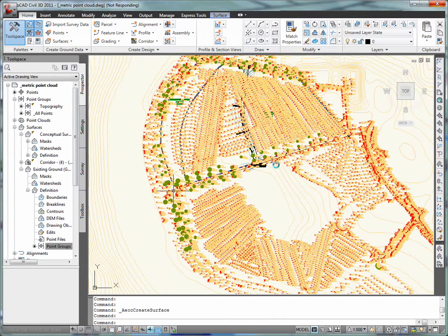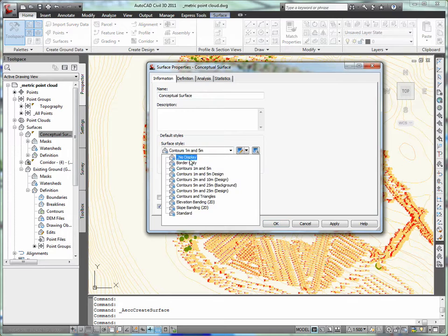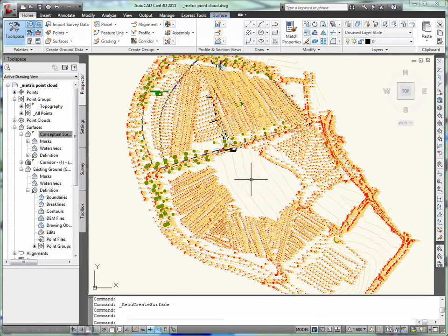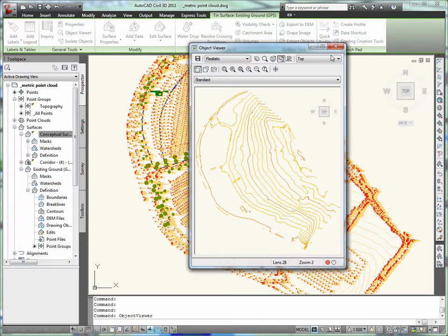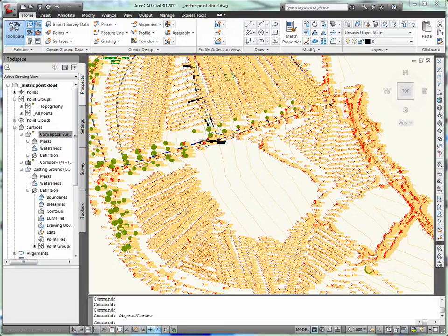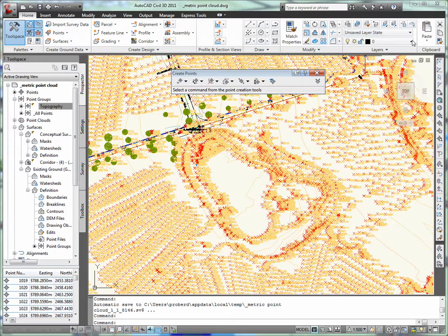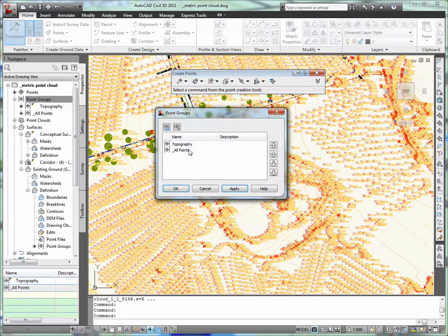In preliminary design, we use the conceptual surface for things like profile views, daylight targets, and more. Now that our project has a more accurate surface model, we can quickly swap it with the conceptual surface without interrupting our design work or requiring the model to be recreated. So we can start with a conceptual surface and continue to refine our model without losing any momentum. Just change some visibility to make things easier.